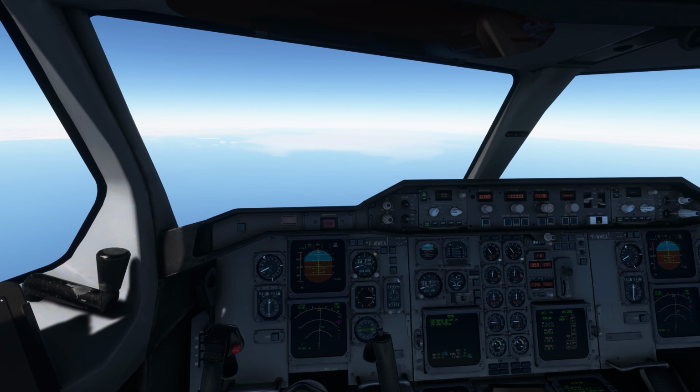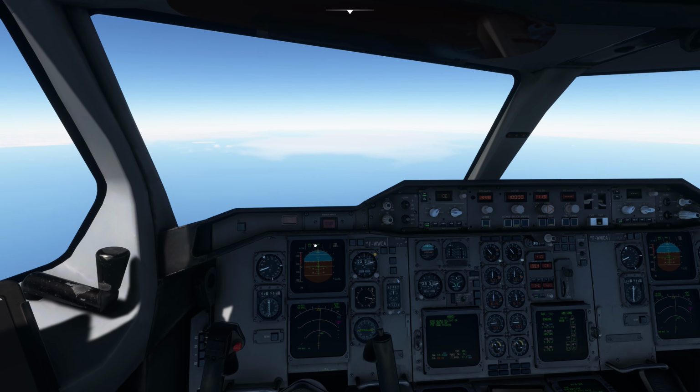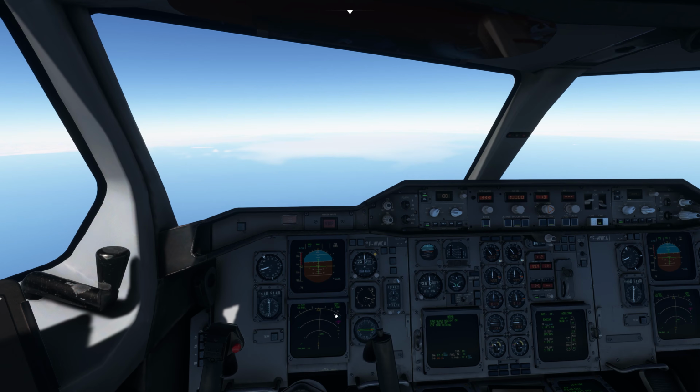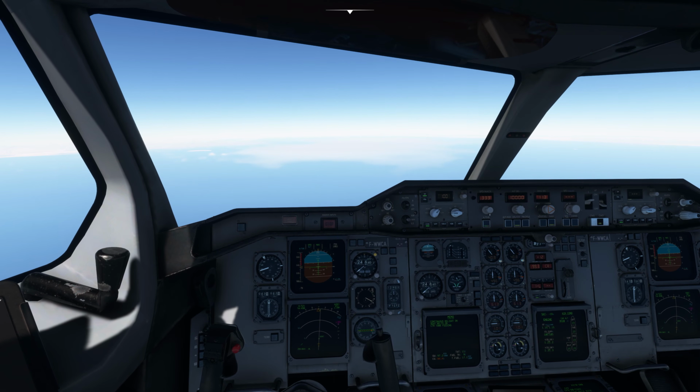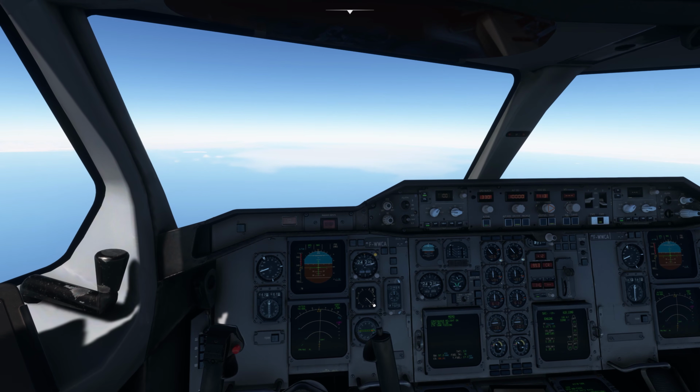I don't know. So you can use the level change method, but in this method you have to actually control the speed yourself, because in the level change what happens is that the plane actually starts to give priority to the speed. As you can see, the speed is coming. So the vertical speed is adjusted in such a way that whatever the speed is specified over here, the plane keeps on flying at the same speed. So if I, let's say, keep it at 330 knots, you can see the vertical speed is getting adjusted in such a way that the speed remains at 330.